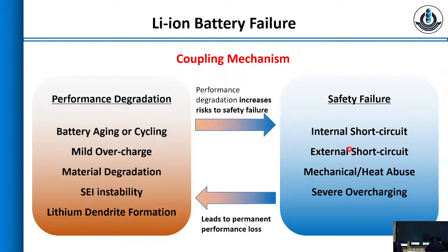So this is what happens to a cell when you are increasing the temperature of a cell individually. But as we are using the batteries with charging and discharging cycles, there is a progressive performance degradation. So as you use more and more batteries, the batteries will degrade. The internal resistance will increase. So with the same heat current, if you extract the same load, your temperatures will rise because of heating.